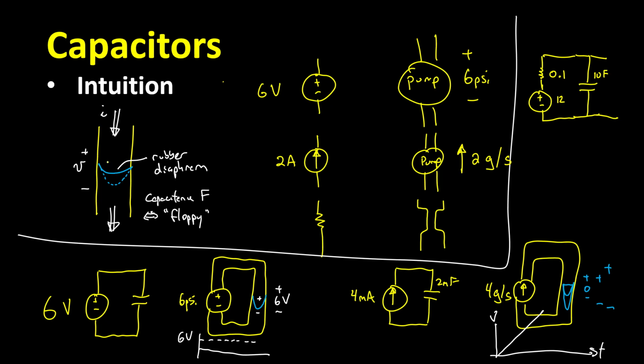And because it's so huge, there's a very large amount of current that it can instantly provide to provide a huge bass thump, far more than the 120 amps that this could provide. And it can provide that very large amount of current for a small amount of time and not appreciably change the 12 volts across it.